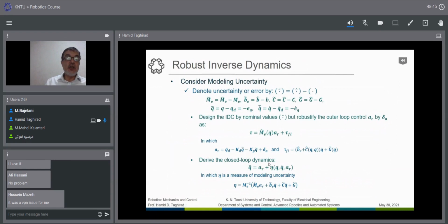If we consider that we know eta, then we consider uncertainty. If we call it uncertainty, it means that we don't know exactly the value of that. Let me explain it in a parametric form, with an example for you. For example, you have a resistance. You buy a resistance off the market, and it says that the resistance is 1 kilo ohm plus minus 10%, or plus minus 2%, or plus minus 1%. But it is never exactly 1 kilo ohm.